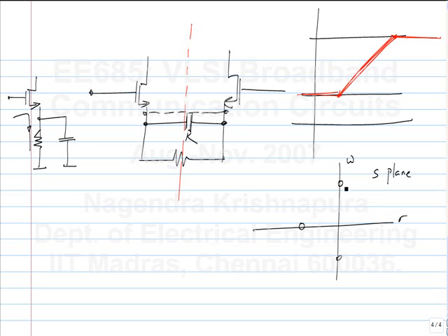If you have zeros on the imaginary axis, for instance, if you look at the impedance of a series LC, it will have zeros on the imaginary axis. So for some sinusoid that you apply, this looks like a short, whereas this 0 is not on the imaginary axis, it's on the real axis. So nowhere does it look like a short, at least for no sinusoid. It is for a complex frequency that you can say it's a short. But the easiest way to see it is that when the capacitance is open and when the capacitance is short, it has to make a transition between the two, and you also know that it's a first order thing, so that will be at the rate of 20 dB per decade. Anything else?